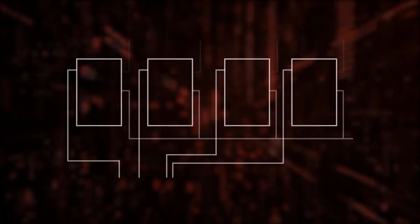Suppose we have an n-bit register, then we do loading for all the n flip-flops at the trigger of a clock pulse. At this trigger, each flip-flop will have a value stored inside it. As I said earlier, the buffer register only stores the values inside it. No other processing occurs. Look at this diagram.